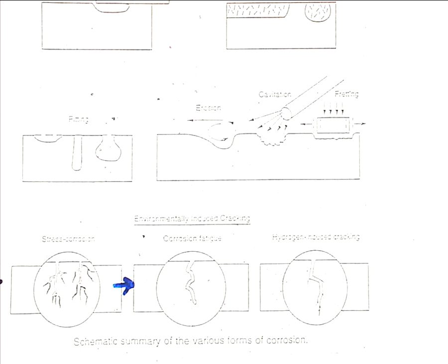And the extreme case of that is at very high velocities in rotors, whether they're propellers or pump rotors or other situations where you essentially run the rotors faster than you should. You can get cavitation, which is the explosive collapse of voids in the solution. So the velocity of the impeller creates a shear stress between it and the liquid. That generates voids, and they can explosively collapse. Okay, it's not bubbles, but voids in the structure.